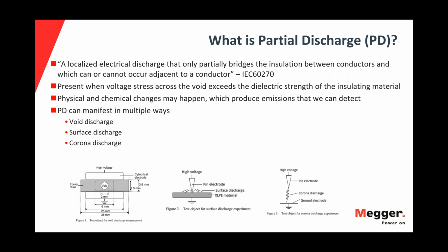It can be a corona discharge, for example, due to the sharp edges, for example, due to the uneven surfaces, whether not a good finish at factory or probably a later stage. It either can happen at factory or in later stage.